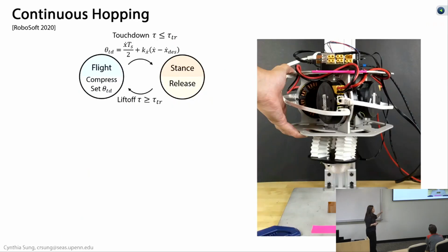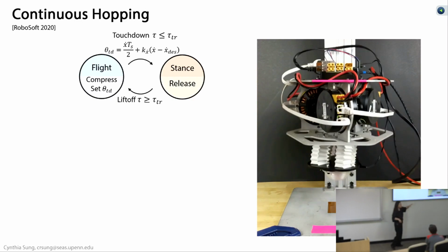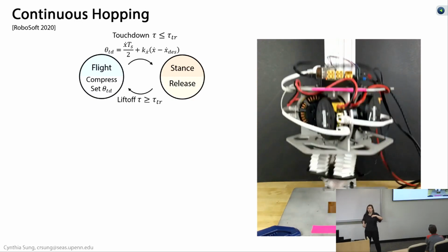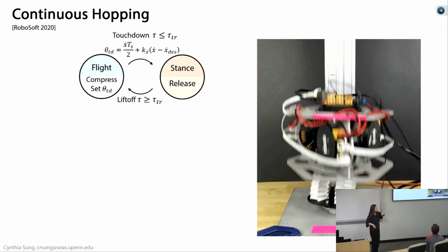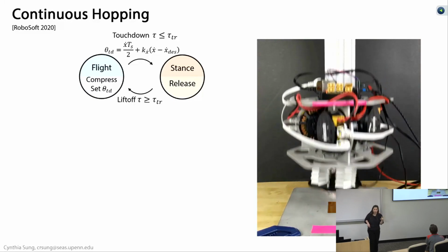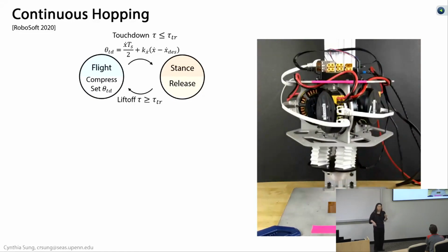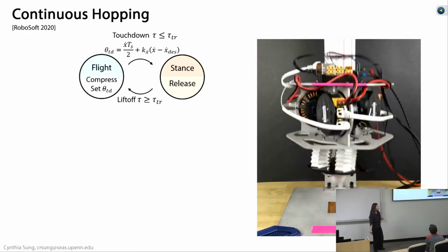So what you're seeing here then is the result of this idea. Right here on the bottom of this robot here is that spring, the one that I'm passing around, this time tuned so that it has a stiffness of 3 kilonewtons per meter. And this robot here uses the exact same controller as the Raibert hopper that I showed you at the beginning, but in this case, the spring for this robot is being implemented as an origami structure, right?